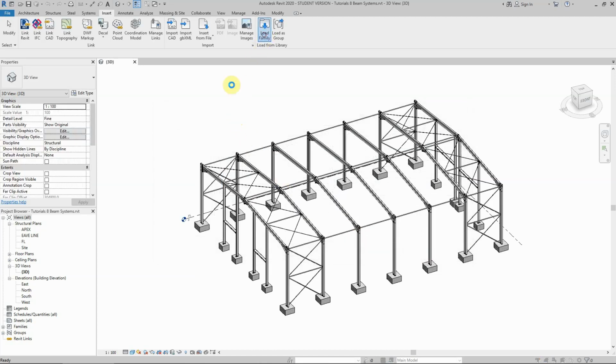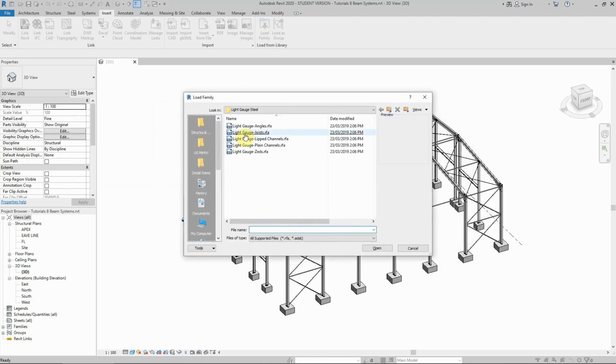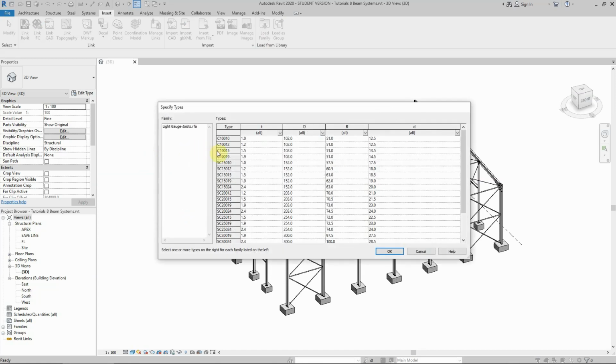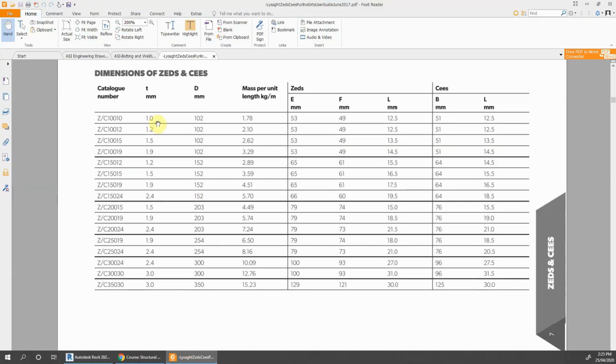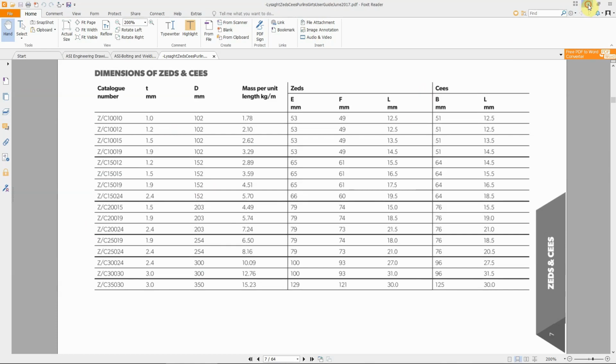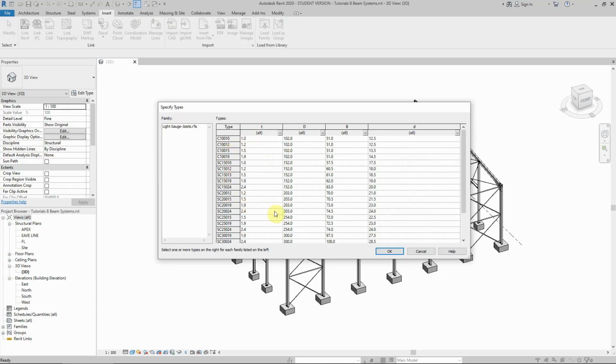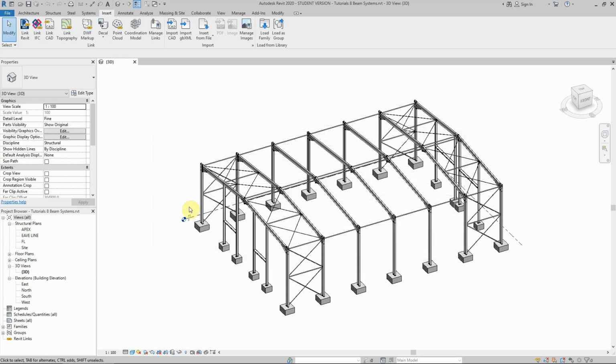Secondly, the second section we may use is the joists. The naming convention on these joists is a little bit better, closer to what we've got in the Australian Lysaght selection or group of sections. The problem with this section, from experience, is that when you insert one of these sections into your model, you can't create connections to it for some reason. When we started looking at the purlins, cleat plates and connections to the rafters, we couldn't insert those. That's why I've created a small family.